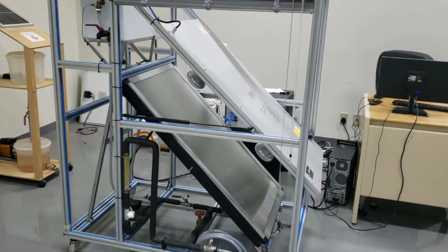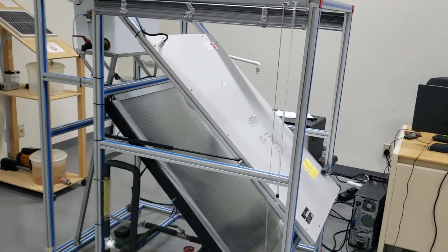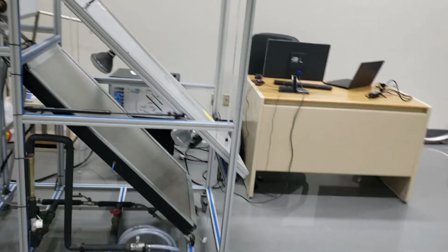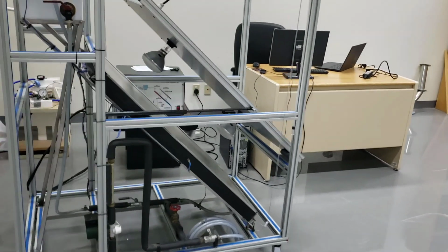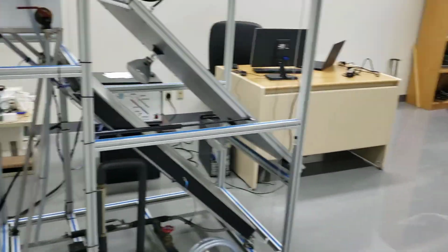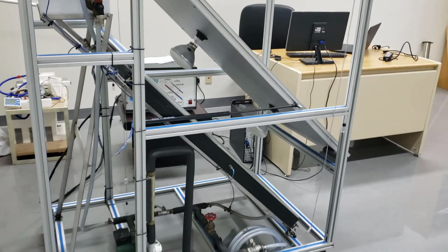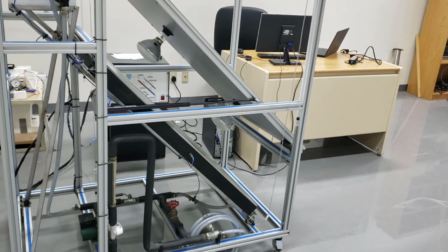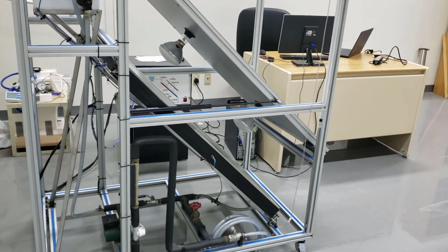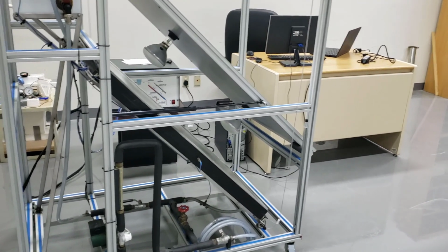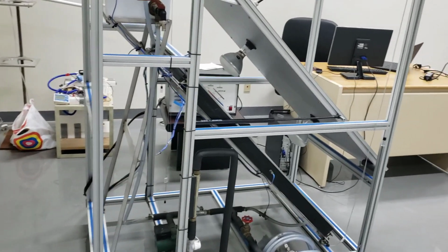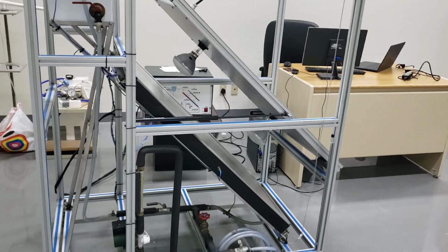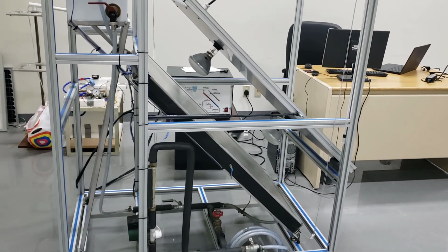As we know, the flat plate solar collector is used to heat water by two modes. The first mode is passive or thermosiphon mode, where the circulation of the fluid occurs due to the buoyancy forces produced by the differences in the densities of the fluid in the collector. The heating of water decreases its density, causing it to rise through the system. The second mode is active mode, where the circulation of the fluid occurs by an electric circulation pump.